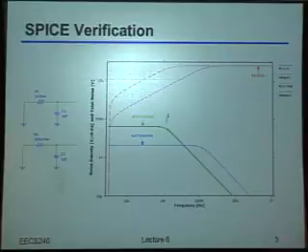So indeed, if you look at this SPICE simulation, which by the way, you don't even have to do in SPICE, you can do this by hand in 2 seconds. But basically, this is the example with a larger resistor but a lower bandwidth, versus the example with a smaller resistor but a higher bandwidth.